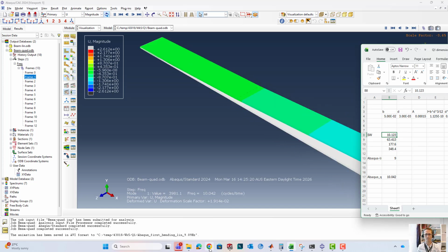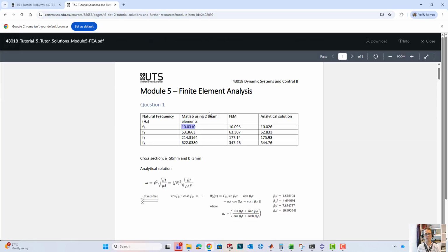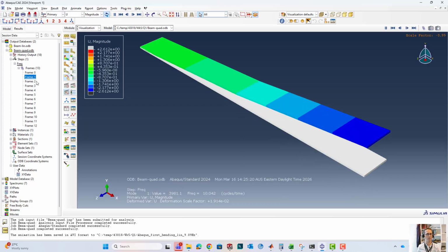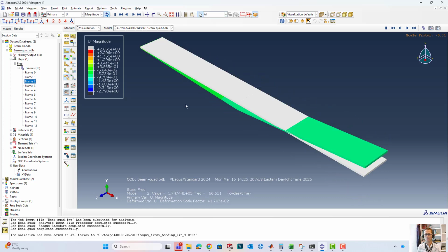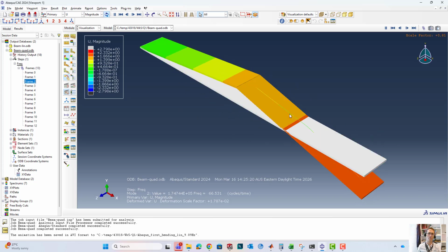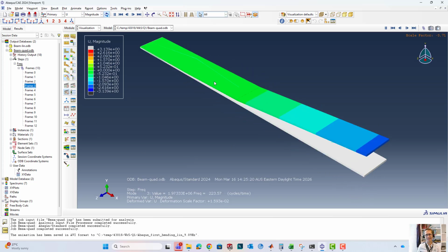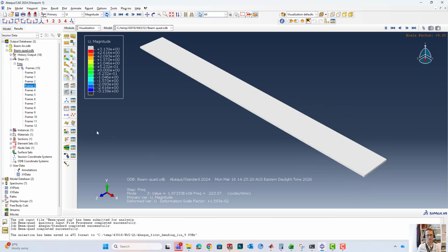So now we're in very close agreement. SolidWorks is a coarser estimate. Abaqus produces a very nice comparison with the answer from MATLAB, 10.03, for this beam type with a quadratic element type. And I can scroll down. You see, however, this is still, remember, only a two-element solution here. This is not like SolidWorks with 5,500 elements. It is literally two beam elements, but because the beam elements are formulated taking into account how a beam behaves in reality, this is what I get to see.